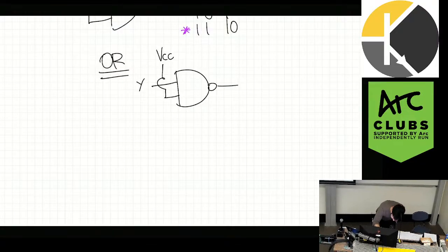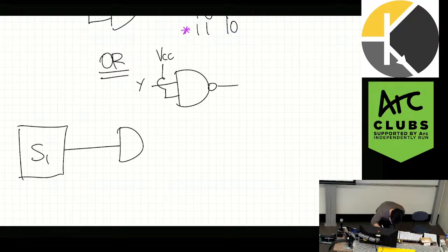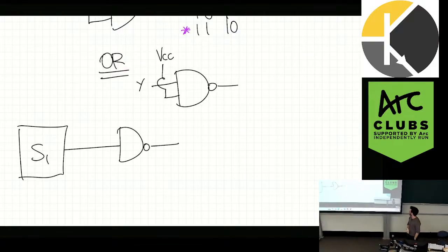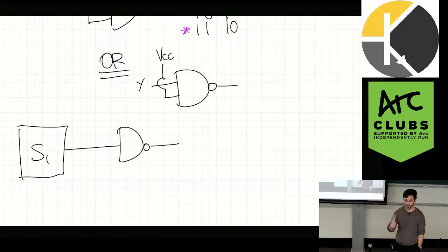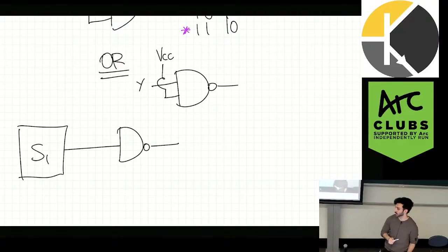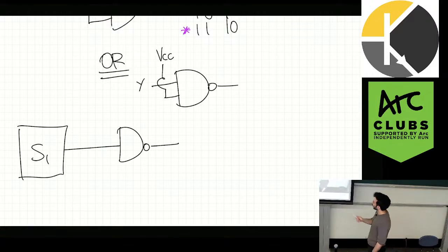Then it asks us to calculate the noise margin, between S1 and the NAND gate. This is the same question. Now, the noise margin is only a useful metric between successive logic gates. It's essentially how high the noise at the input can be before the output stops recognizing it as what it should be.